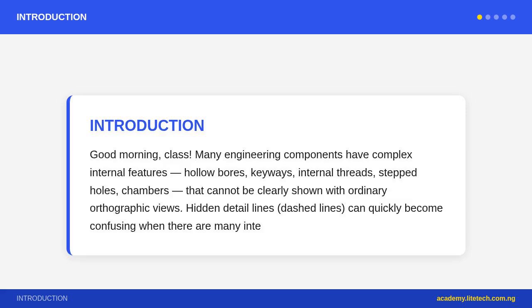Cut surface hatching. The exposed cut surface, where material was actually cut, is shown with hatching, thin parallel lines at 45 degrees, evenly spaced, typically 3 to 5 mm apart. Adjacent parts in an assembly are hatched at different angles, 45 degrees versus 135 degrees, or different spacing, to distinguish them. Do not hatch through a hole. Hatching stops at the edge of the hole.